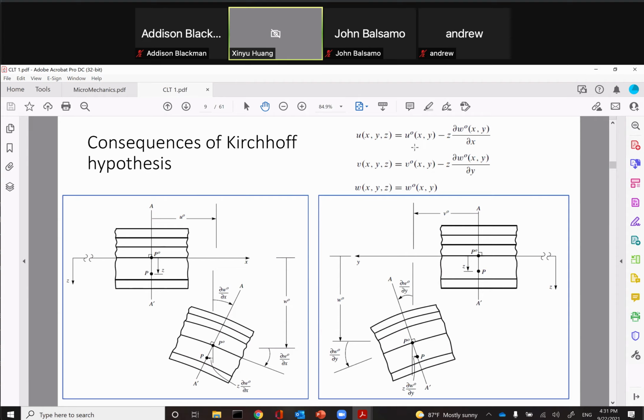All right. And also this point has moved a little bit. So you can have a displacement function that describes how this point moves. The u function describes how every point moves from the original configuration to the new configuration, right? If you know the coordinates, you pick a material point x, y, z. You plug it in here. This tells you how much this point moved in the x, y, and z direction. That's what we call the displacement function, right? It's called a motion.